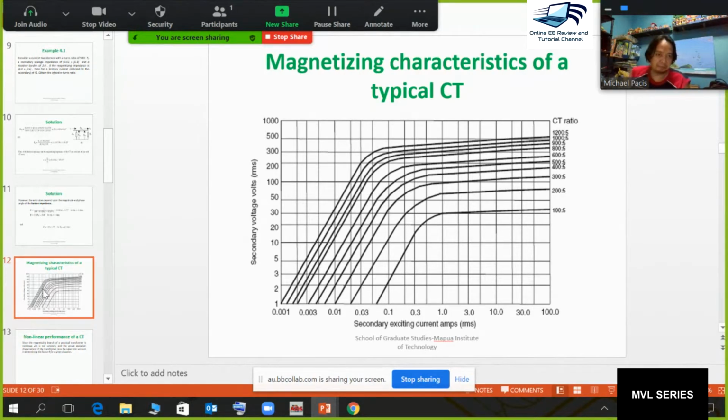Because you already know, this is dynamic. The transformer has a dynamic response. What we have described from the first example was considering a linear relationship. But here it does not have that. It has these curves, knee curves. So if you want to use these knee curves, this is the true value of your CT ratio, and we can make use of this as an example.